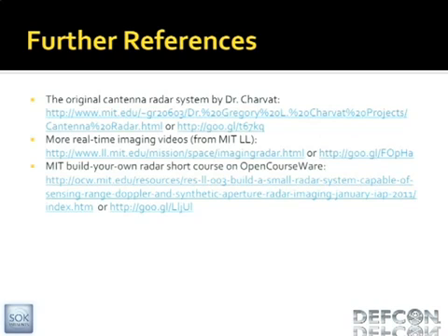But if they're not transmitting, it's not really a big deal. Is the upper frequency limit defined by how easily you can obtain a reference signal? The frequency bands that you can operate in are mostly a few bands. You pretty much are stuck to the ISM bands if you want to do this legitimately, because those are licensed for this unrestricted or pseudo-unrestricted use.